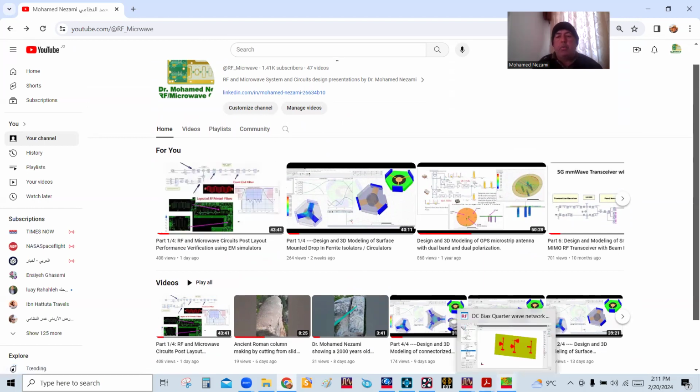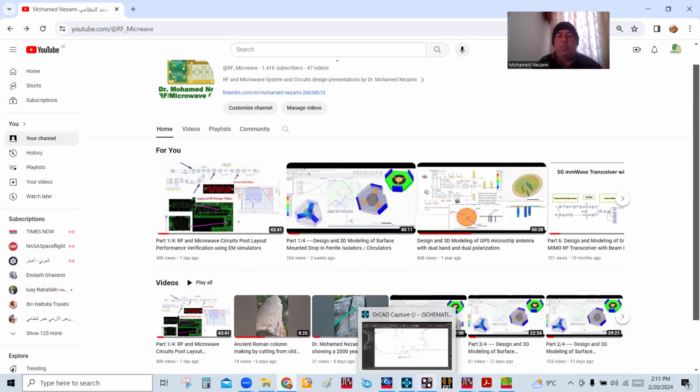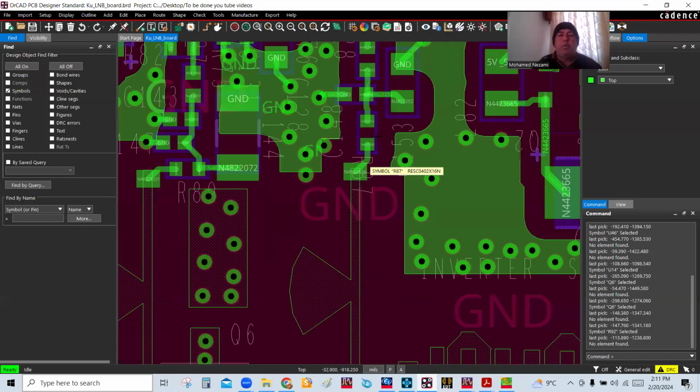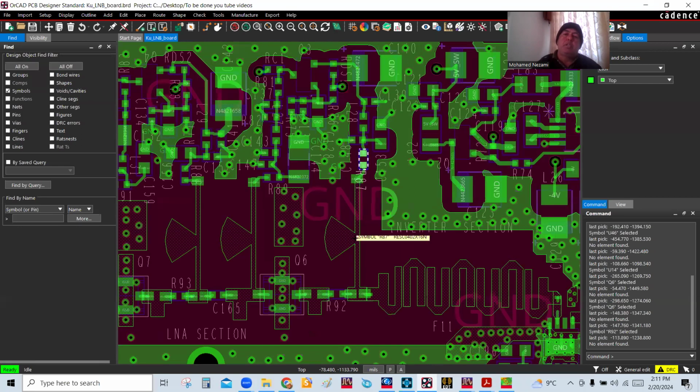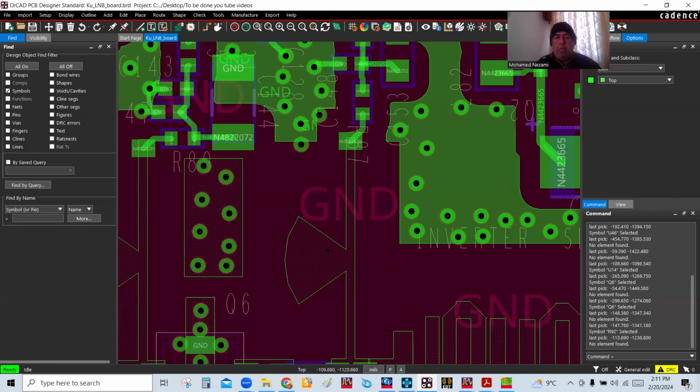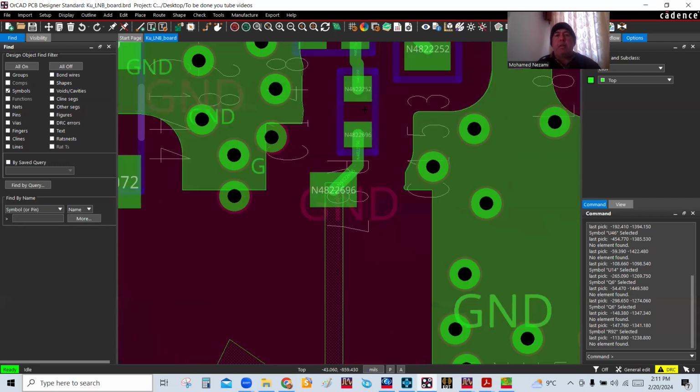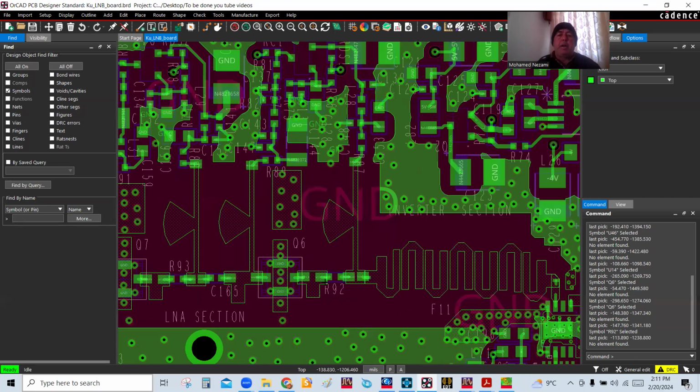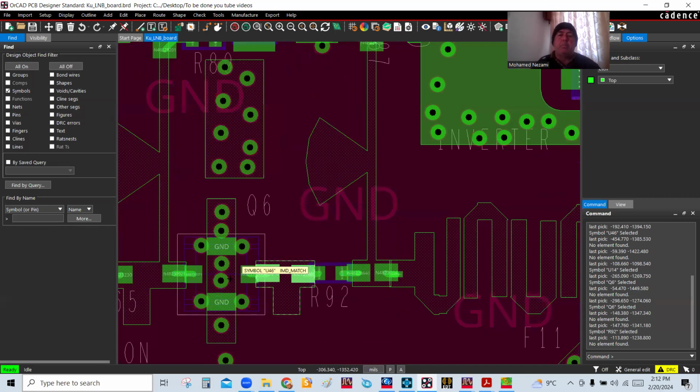So next, I think what we will do is we could probably start introducing a co-simulation concept where we will include the effect of these passive components and make an EM symbol out of this and use it in schematic-based simulations where we can engage the EM model along with the S parameter file model and even the large signal model or the S parameter model for the active devices. Okay, so we'll see what happens on the next session.